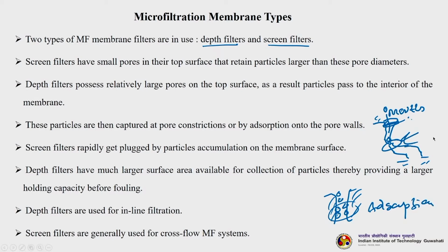Screen filters rapidly get plugged by particle accumulation on the membrane surface. Depth filters have much larger surface area available for collection of particles, thereby providing a larger holding capacity before they get fouled. So, depth filters are used in inline filtration, and screen filters are usually used for cross flow